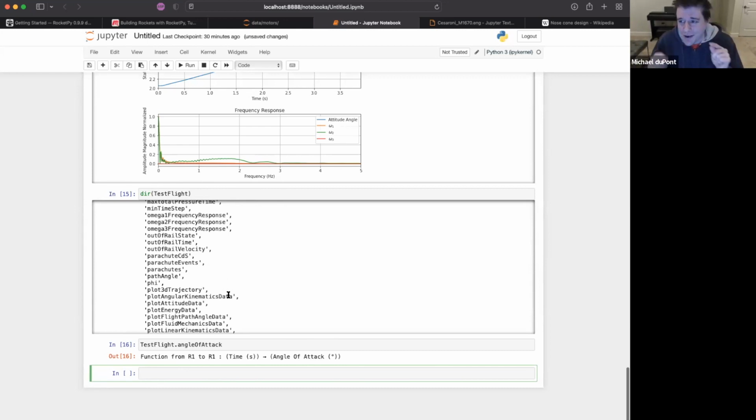Now if you look at the graph and it goes right off the launch stand, I would say that's not a successful flight. If you wanted to make it automated, like was this even a reasonable flight, you could check something like: is the time of impact of my flight greater than the amount of time that the rocket motor was supposed to burn?